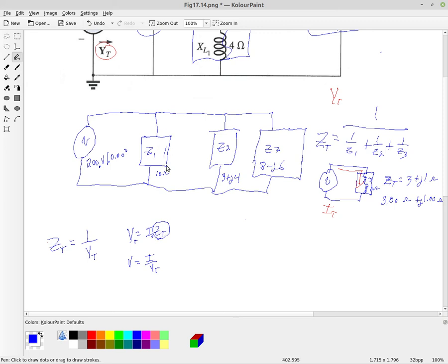And for parallel circuits, a lot of times they like to write those as admittances, because if you called this one the admittance Y1, and this was the admittance Y2, and this was the admittance Y3, in a parallel circuit the total admittance, Y total, is simply equal to the sum of the parallel admittances.